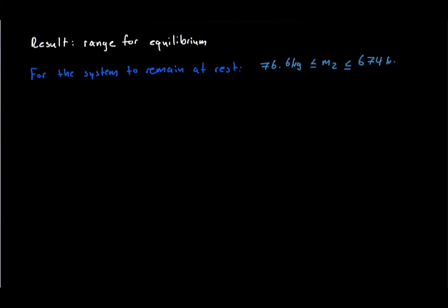The key lesson from this problem is that the pulley contact angle must come from the actual rope geometry. In our setup, the relation 90 degrees plus alpha works only because the right-hand rope is parallel to the incline, and the left-hand rope is vertical. After the contact angle is known, the rest of the problem is handled by considering the two possible impending motions separately. When the motion reverses, friction on the block reverses, and the high and low tension sides of the rough pulley switch as well.